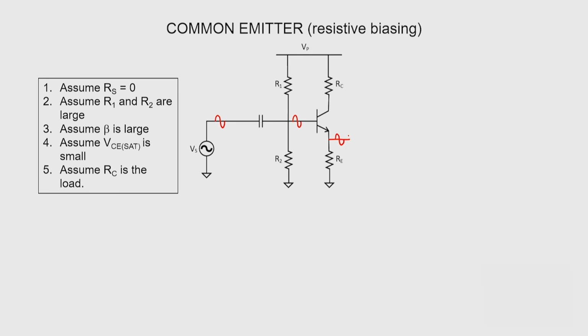In order to simplify things here a little bit, we're going to maximize our gain and assume that this emitter resistor equals 0. We're still going to have to be careful not to cause the transistor to go into saturation or cutoff, but this will maximize the gain in any case. That AC signal will show up at our collector. And now the questions I want to talk about are how low it can go and how high it can go before our transistor starts to have a problem.